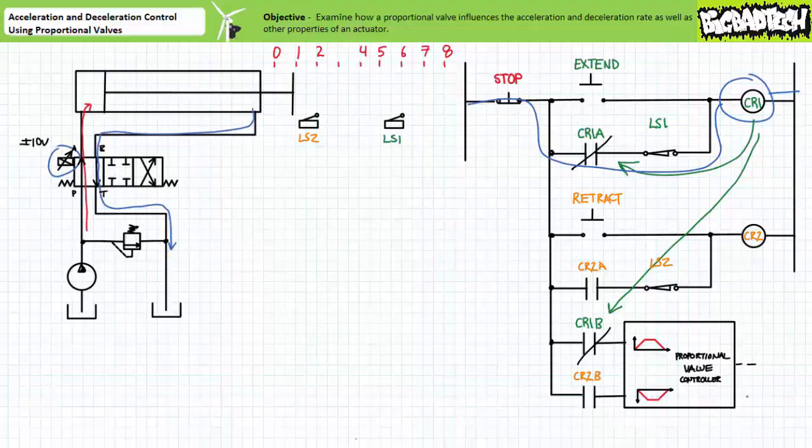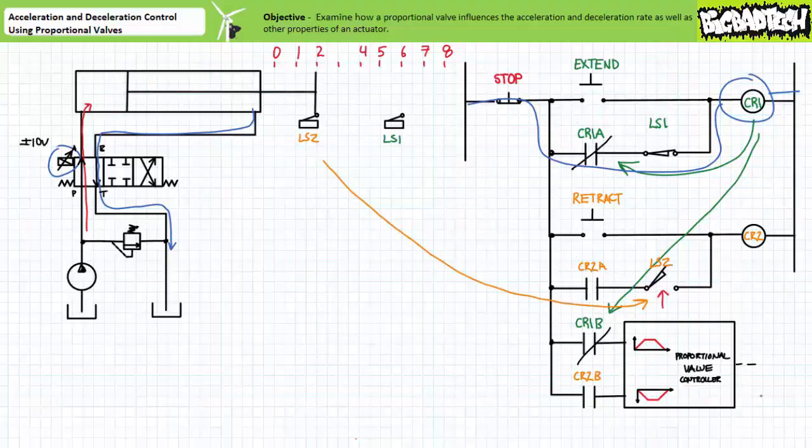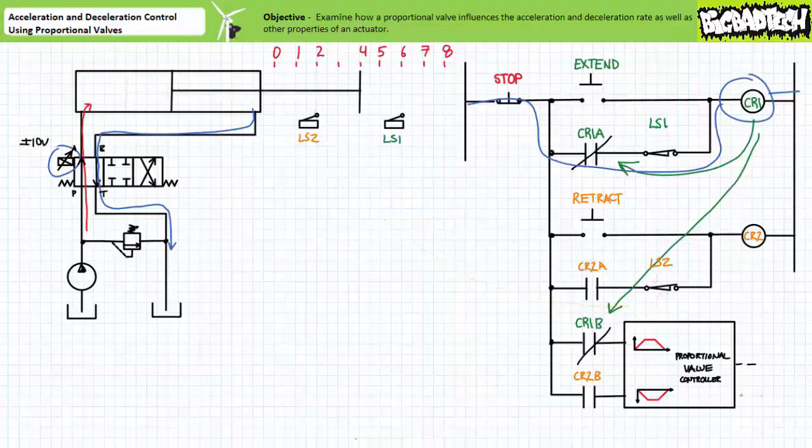Flow rate goes from 0 to maximum, and the cylinder applied load suddenly jackrabbits to a start. Pressure immediately drops to that necessary to extend the applied load. Let's say 100 psi is sufficient. The cylinder extends. 2 inches into the 8-inch stroke, the applied load strikes LS2, but no output is observed since normally open contact CR2A is still in the deactivated open state. Leaving the reset region of LS2, LS2 recloses.